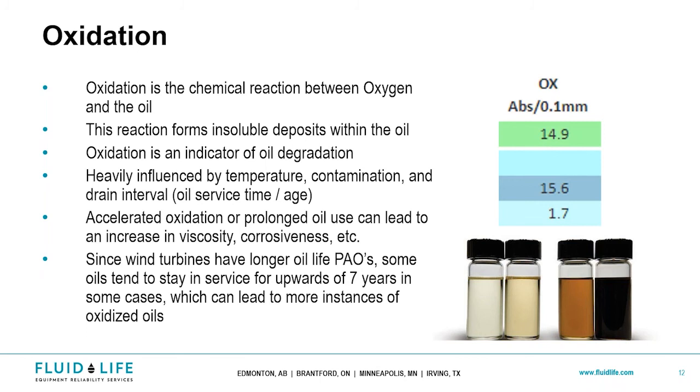More abrasion is usually not a good thing in most systems, right? Oxidation is a pretty good indicator of not only the degradation of the oil, but just the age itself. It's heavily influenced by temperature, it's heavily influenced by contamination, it's heavily influenced by how often you're draining it and topping it off.